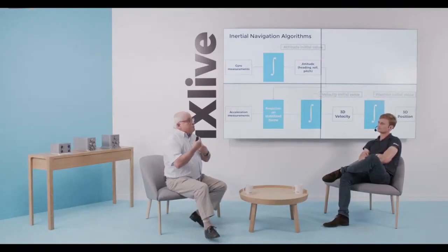In order to measure the direction of this Earth rotation rate, we consider that at least you need an accuracy in the measurement of 1/100th of this Earth rotation rate. So it means that you need some gyros which have an accuracy better than 1/100th of 15 degrees per hour, so a little bit more than 0.1 degree per hour.